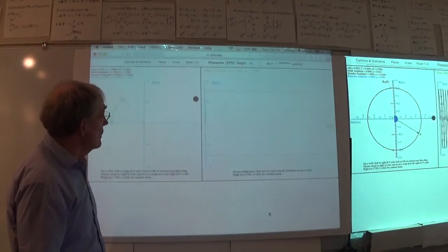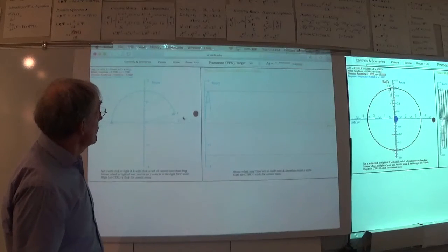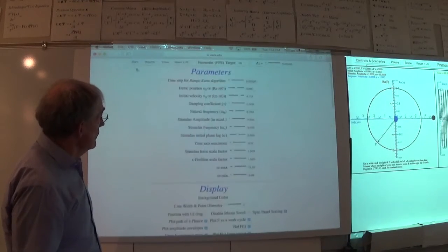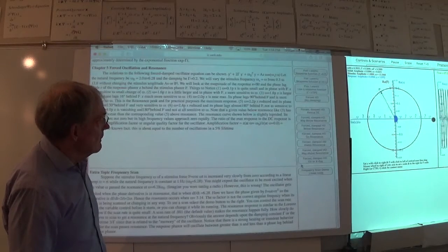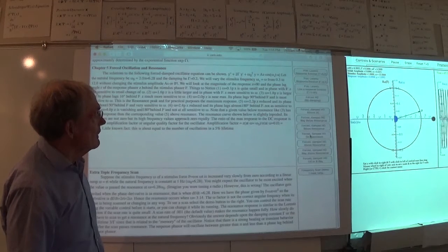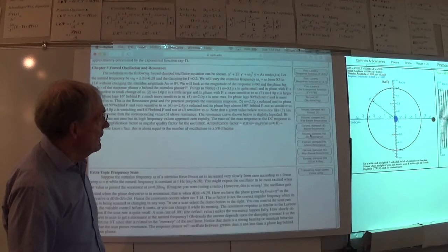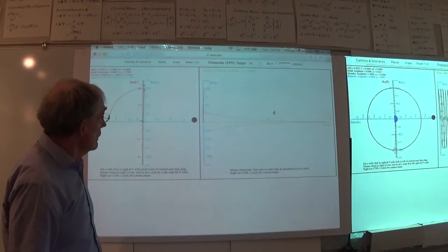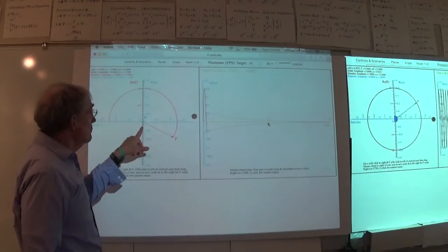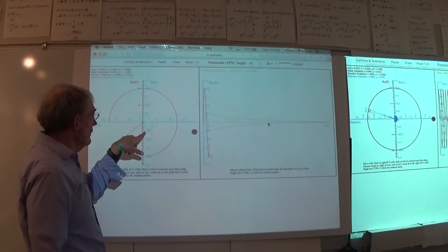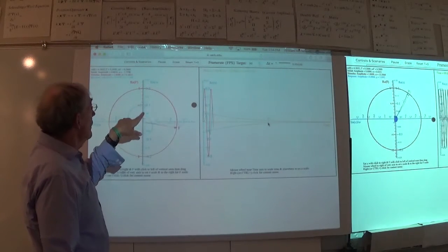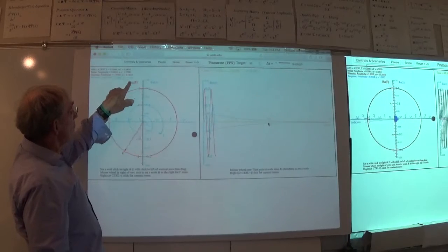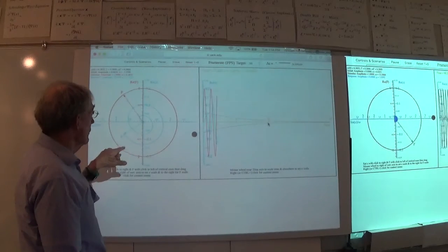Because this is where the complex variables stuff really helps us to tackle this thing. So we'll once again do the on-resonant case just to get an idea about that. But you see, what really happens in that particular case is the transient wants to take this thing to some other phase lag than 1.57, that's pi over 2.